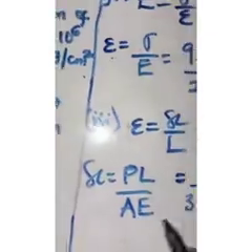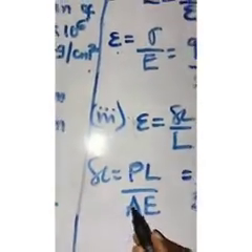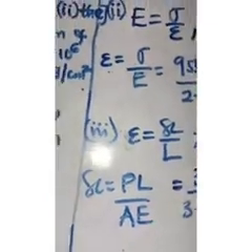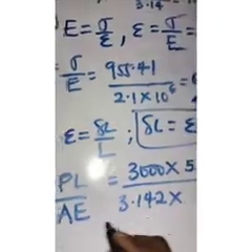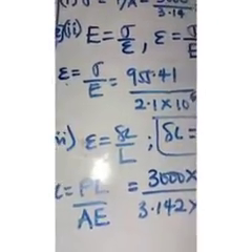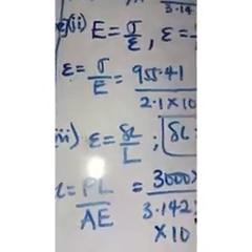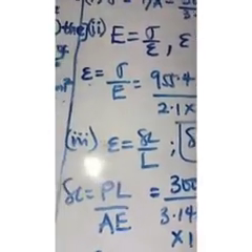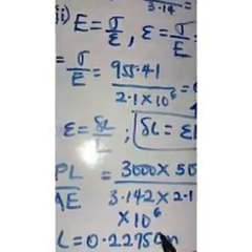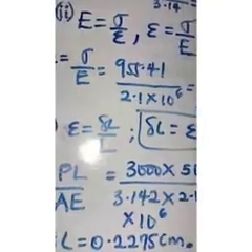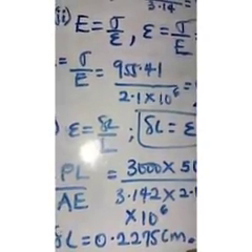You remember, right? That is your original formula for Young modulus. So I'm going to have 3000 times 500, 3.142. My E will now be 2.1 times 10 raised to the power 6. So I can have my change in length as 0.2275 centimeter. Okay. Alright, so next question.